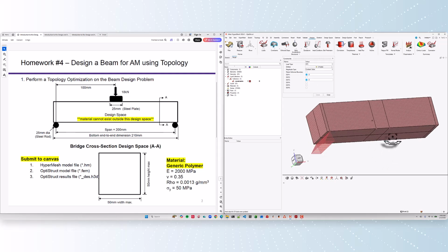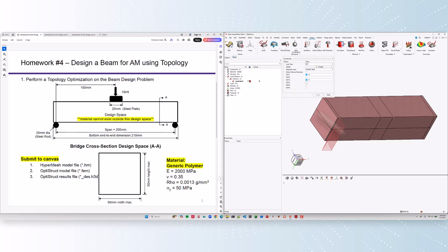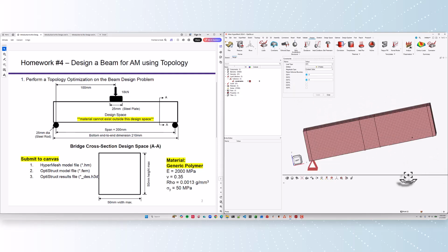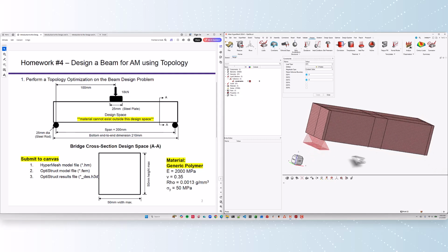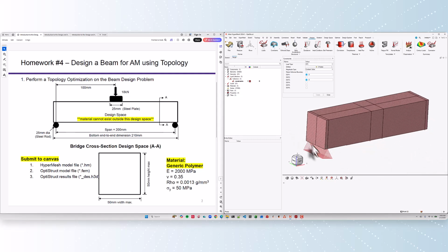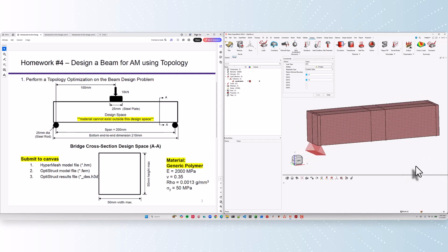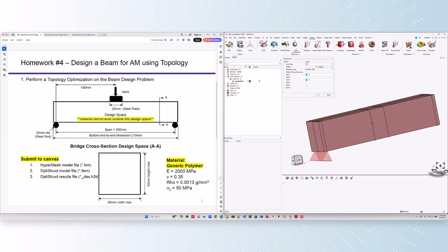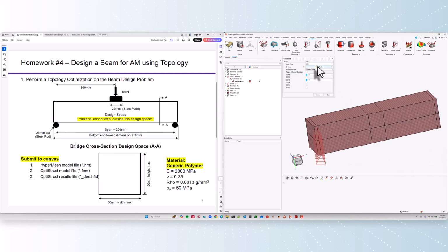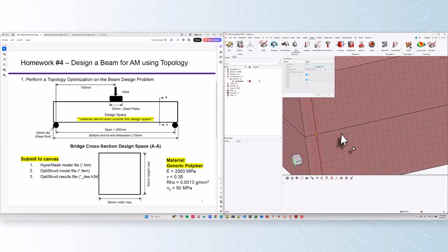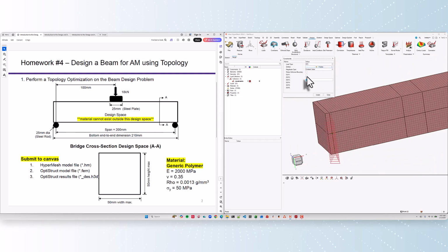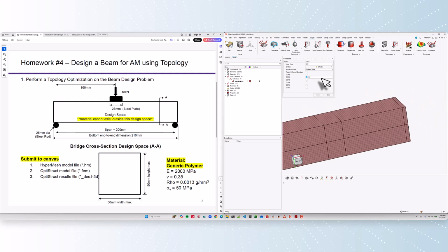So when I say create on this side, I did X, which is DOF 1, and Z, which is DOF 3. Okay, but for rigid body, I still need to fix a Y. There's nothing keeping this block from flying off in the Y direction. But I want it to be able to shrink in the Y direction freely. So to do that, all I do is pick just the center node of the roller and say that center node cannot move in Y. Just basically telling the roller, hey, you can't go off, and that's it. Okay, now we can do the other side. And I'm going to pick my nodes by path again.